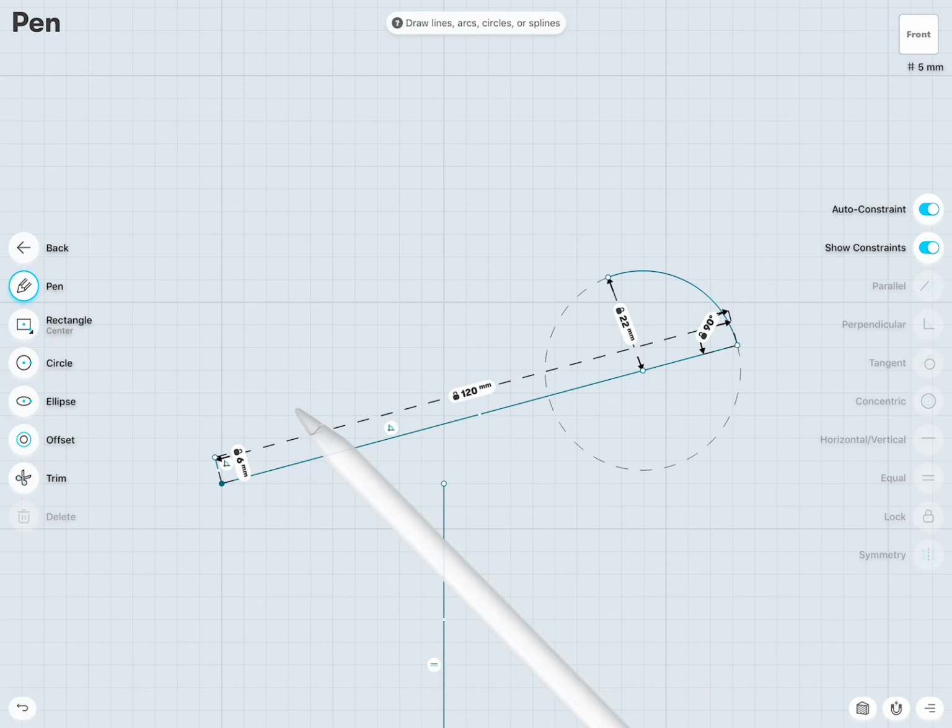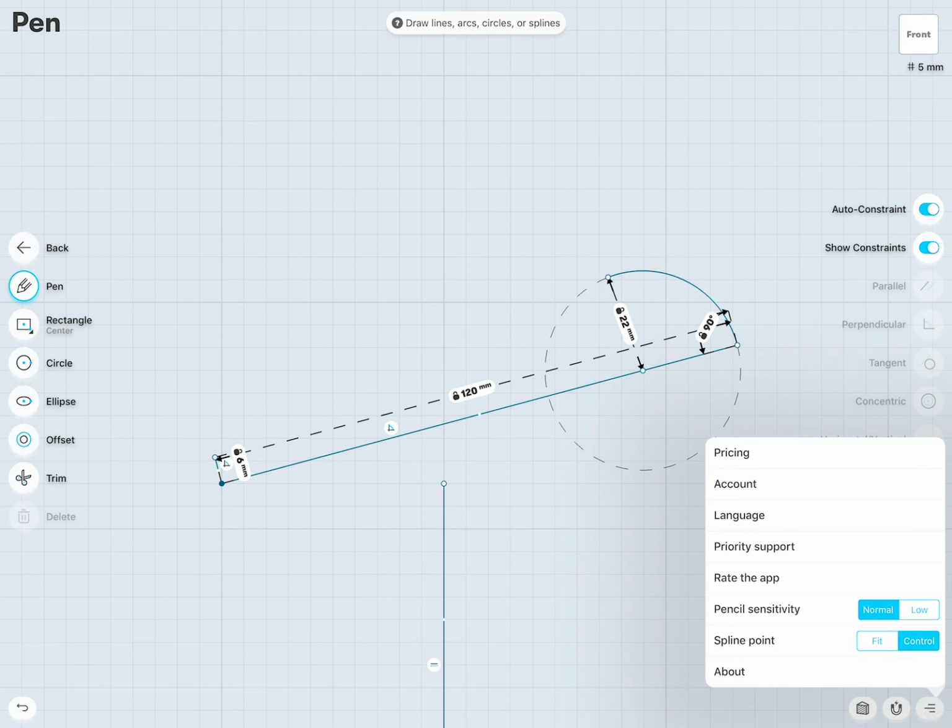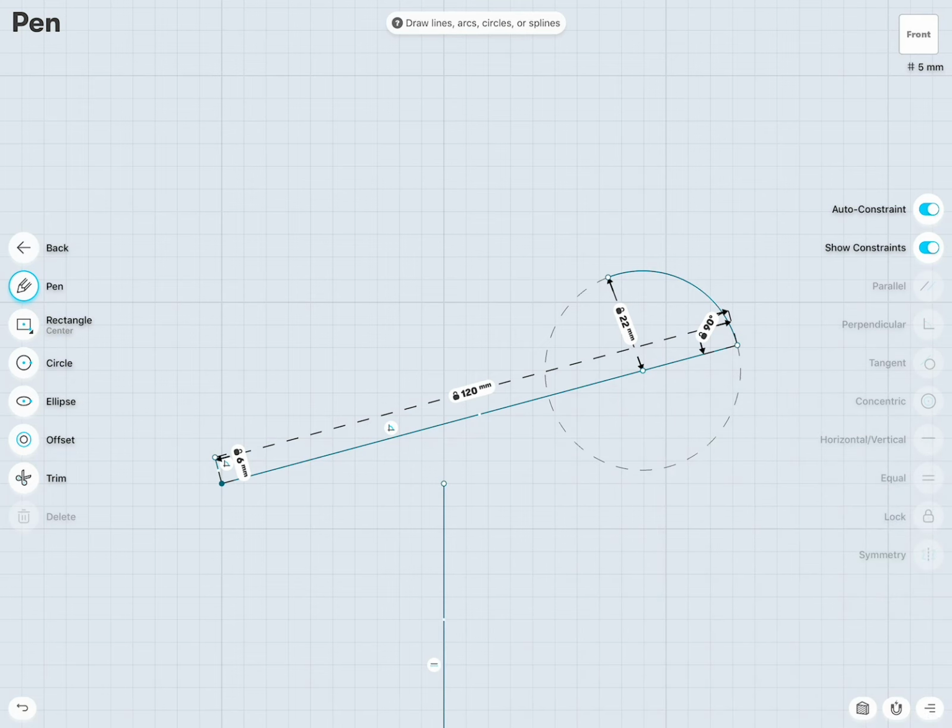Very nice. And let's make a nice smooth curve, a transition. So I will, in this case, use the CV, so control point. From there I start drawing, click, and then I click and I move the last point to there.